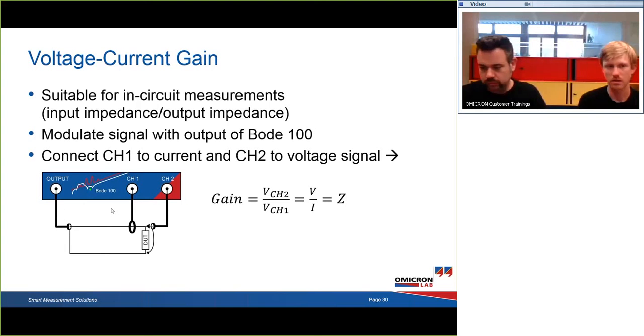However, if you have very low voltages, you can also use the shunt-through method. But the Bode 100 is not designed for DC voltage, so everything above 3 volts DC can be dangerous to the Bode 100. Then you need current injectors or DC blocks or whatever. There are many possibilities to measure output impedance. The current injector method is just the one that is very convenient.